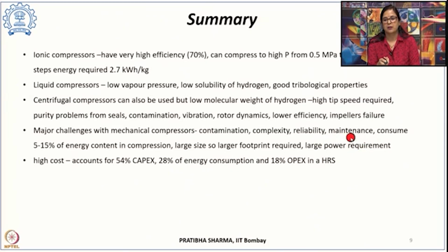At the same time, they consume a lot of energy in compression. Typically 5 to 15% of the lower heating value of the hydrogen being compressed goes into the compression, depending upon which particular technology we are using.